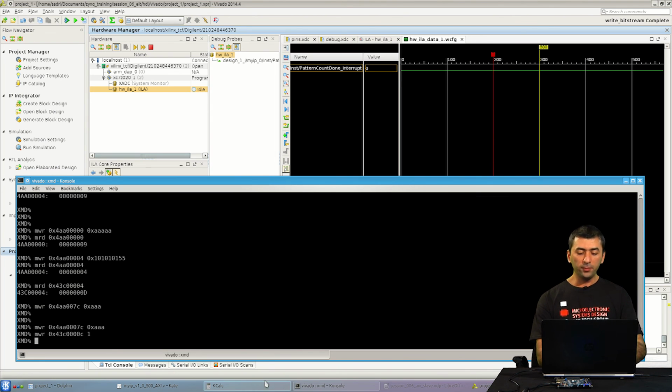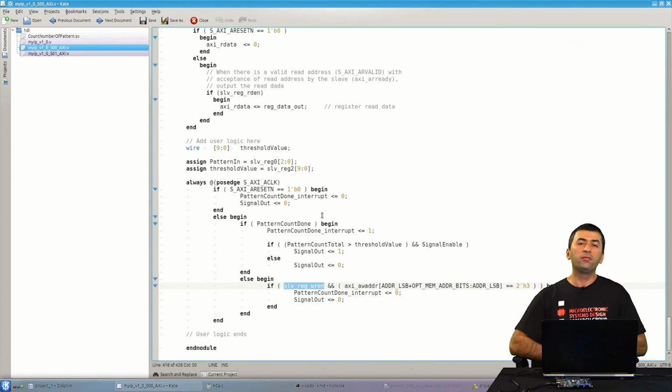Okay, so what we did through this lesson: we briefly had an overview of the signals of AXI slave interfaces. We compared AXI slave full and AXI slave light interfaces. And then we developed a sample hardware accelerator that was responsible for performing a kind of acceleration task that can be used for database applications. It was a very simple accelerator, and as you saw, the creation of the RTL is not that difficult, but at the same time, it is not that easy.